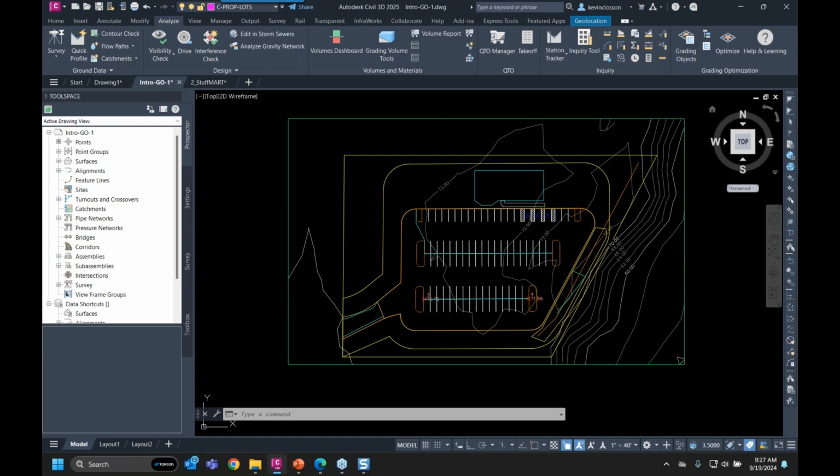A prime example, we were talking about a while ago, is a retaining wall. Once we set that up, you could say, okay, here's my minimum and maximum elevations that I want at the top of the wall, and it's going to still try to work with all those other elements as it goes, and see if it can't resolve that design.